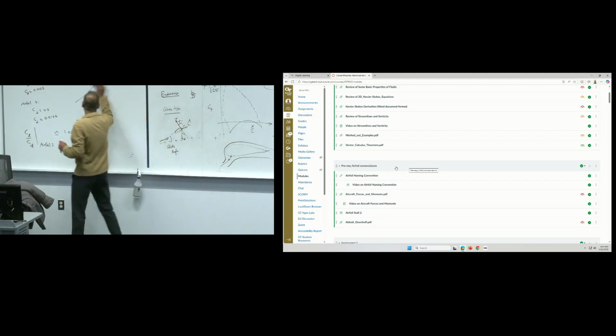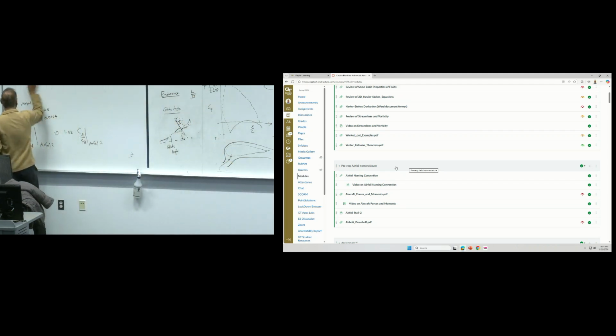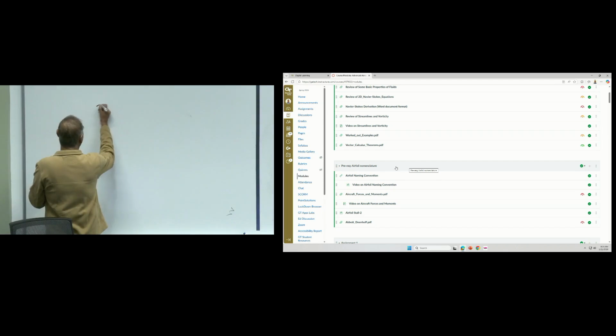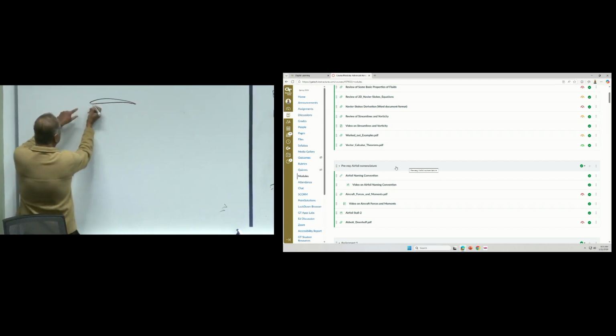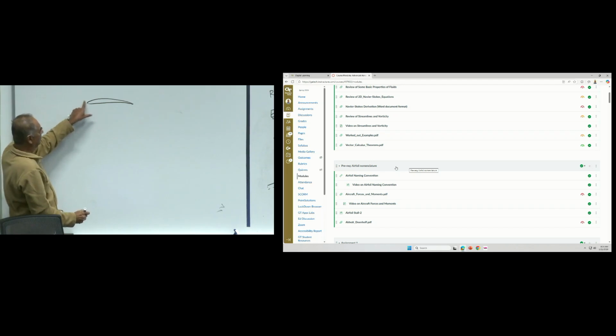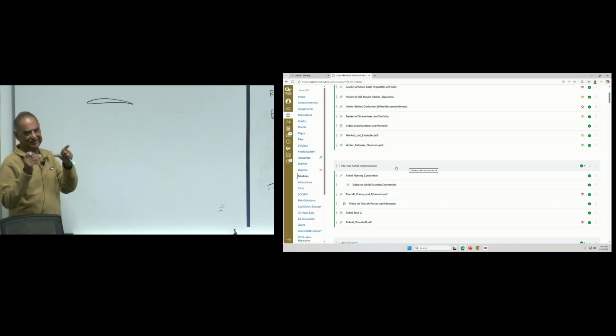Now, certain aerofoils have a very peaky pressure distribution near the leading edge, especially sharp-nosed aerofoils or low radius of curvature aerofoils. Some aerofoils will have a very small radius of curvature, a very rapid variation in the curvature.